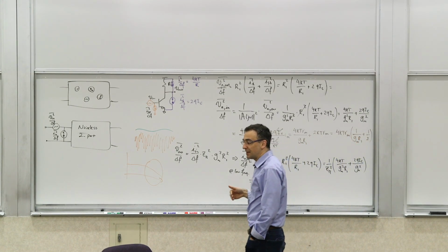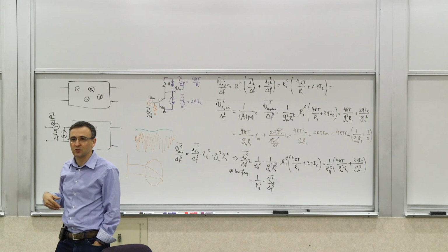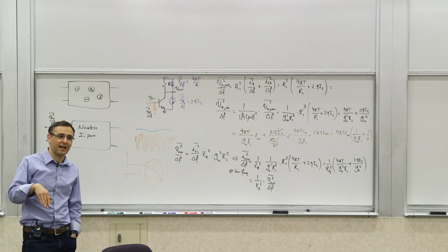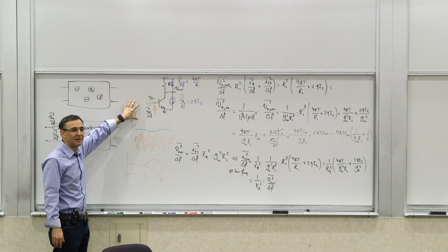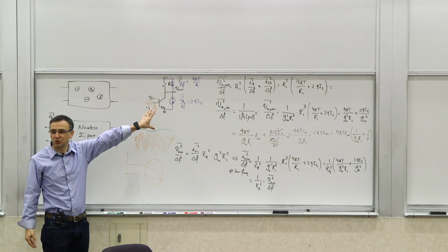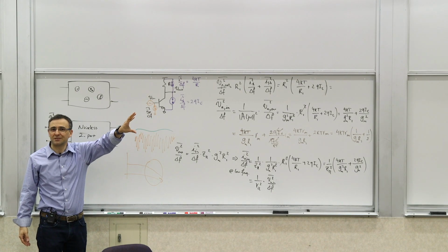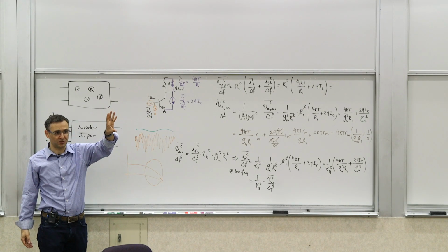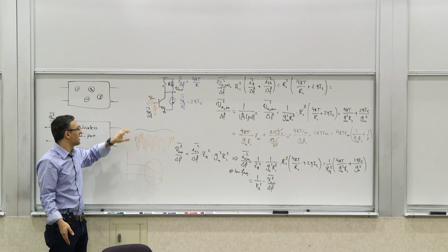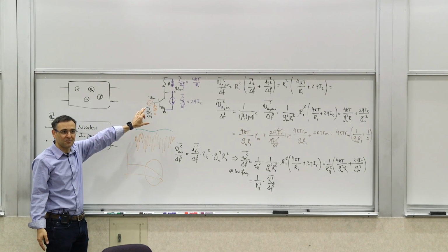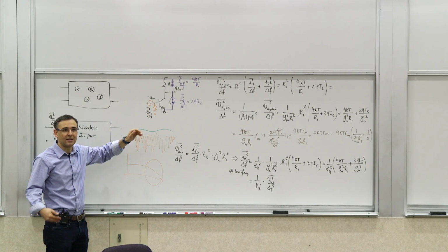There are ways that make it a little bit independent of this thing, like two temperature measurements where you basically set the device with two different sources. It could be the same source at two different temperatures, or you emulate the effect of having a resistor at low temperature and a resistor at high temperature. Sometimes you actually physically do that. You cool something down and measure it, and then you heat it and measure it again as a noise source.